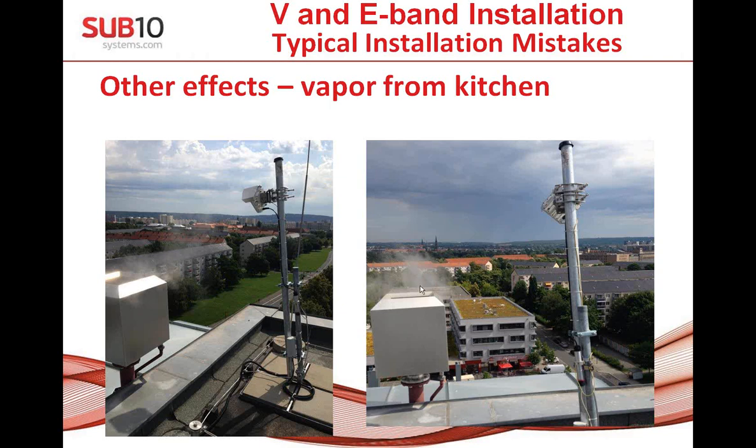but if they are, for example, preparing some steak or hamburgers, there is much bigger steam going out, and it's really hot air which is affecting your signal. In this case, you will probably detect an issue on the link, that the link is dropping from time to time. If you look at the time, you will probably see that it's just before lunch or dinner preparation. Yeah, this is again a bad installation, because this chimney is producing hot and very wet airflow, which is going close to the unit.